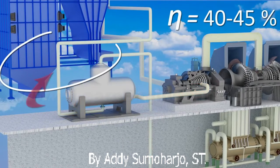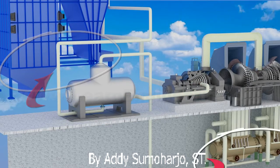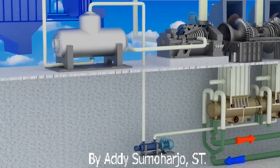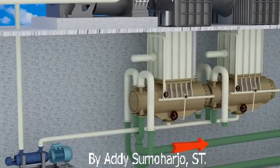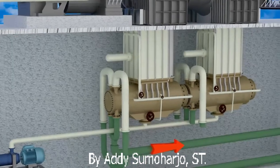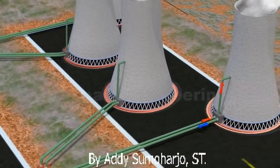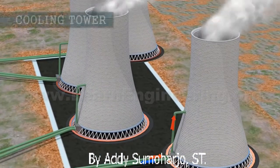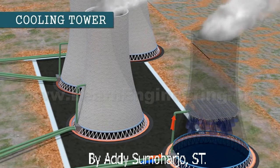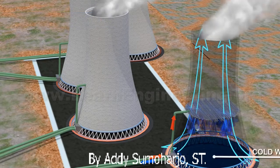Now we'll take a look at how heat addition and heat rejection are executed in an actual power plant. The cold liquid is supplied at the condenser with the help of a cooling tower. The heated up water from the condenser outlet is sprayed in the cooling tower, which induces a natural air draft, and the sprayed water loses heat. This is how a colder liquid is always provided at the condenser inlet.